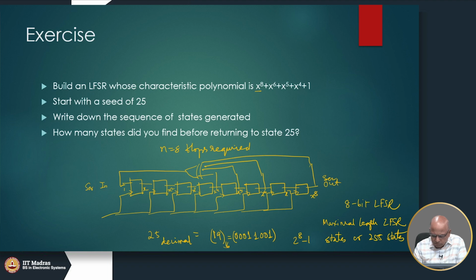and then the machine will begin to generate random values in the register, and it remains to be seen whether all the 255 states are getting generated, right. So, we believe that the answer to this question is 255 states, or 2 to the power 8 minus 1 states.